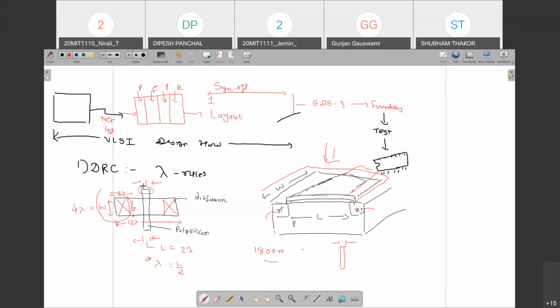This is the job of the software, but you have to pass your design with the DRC check. Is it clear, all of you? Yes, sir. So the first checkpoint we discussed is DRC, design rule check. Once you are working on the layout, this is the very first checkpoint. You cannot neglect a DRC error, otherwise the foundry people are not able to fabricate your design.